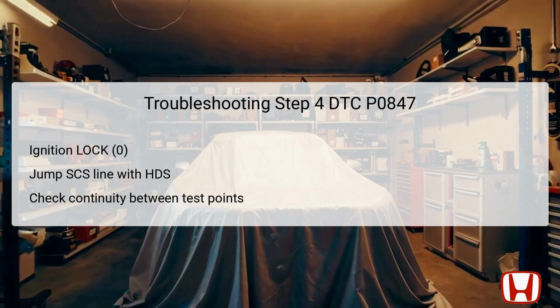After disconnecting, the technician will perform a continuity check between defined test points using terminal number 1 from the 1P connector and body ground. This procedure helps to diagnose whether any wiring issues exist, which could cause the low circuit conditions indicated by DTC P0847. If continuity is present, further inspection or repairs are essential. If absent, it suggests the wire is functioning without faults.